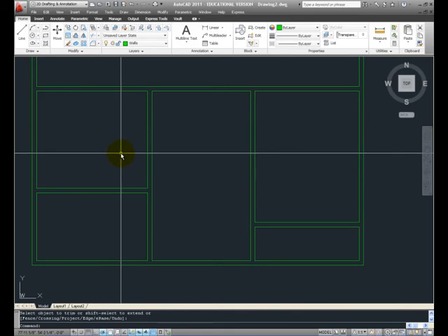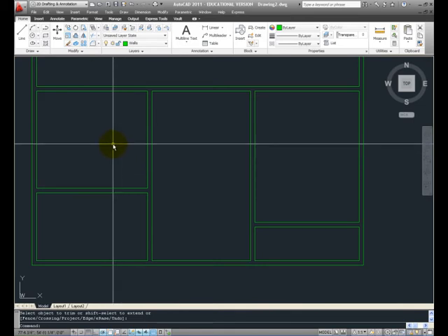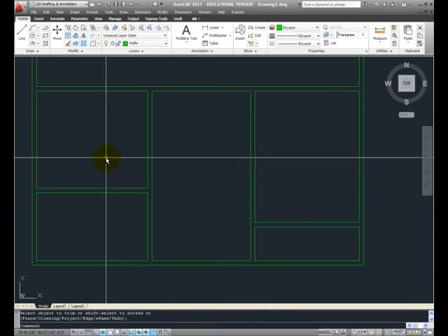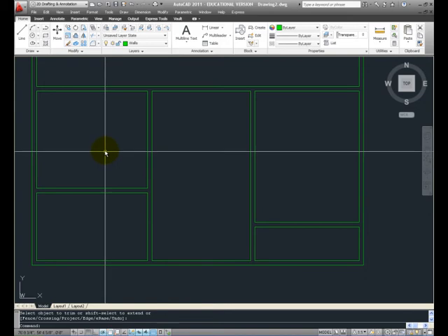In this drawing, there are several door openings, none of which have a dimension provided for them with respect to their size nor their location. So for the purposes of this exercise, we're going to assume that all door openings are 3 feet wide, and then the placement of those doors will be similar to whatever is shown on the handout.